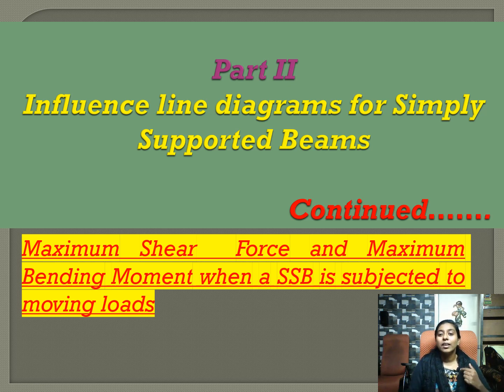Now, I repeat, what we did so far was the shear force and bending moment for a section for the given loads. Now we are going to find the maximum bending moment and maximum shear force. For these problems, the position is not given. The condition given is that the loads are moving either from left to right or from right to left.